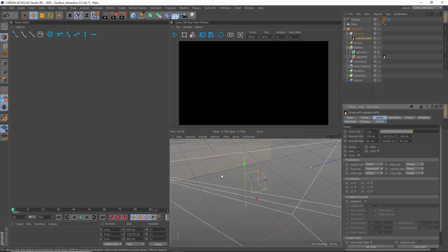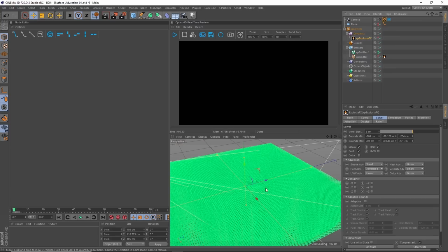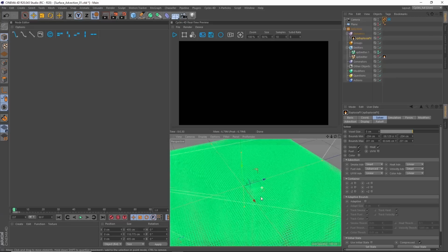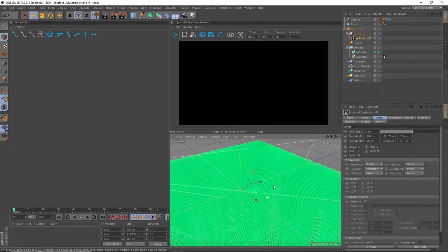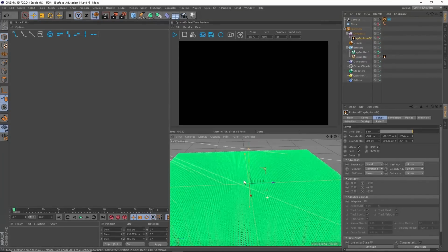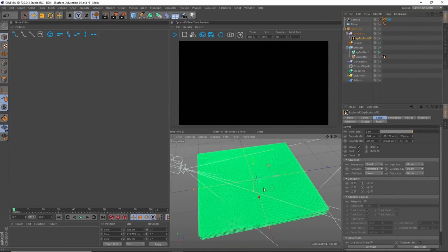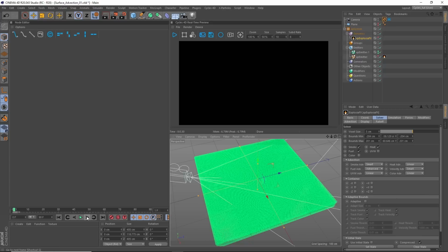But for some reason, a quirk on frame 0, we're getting this adaptive bounds. The result is, if we make that invisible again, on the following frame, particles that were within it are being advected in their rotation, and we're getting this cube of advected particles, which is wrong. Then we move forward the next frame and it goes correct again and the simulation begins.